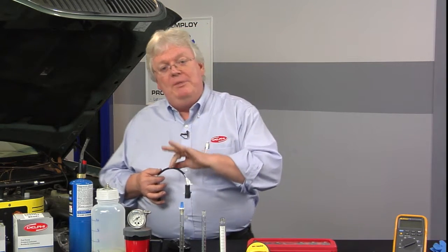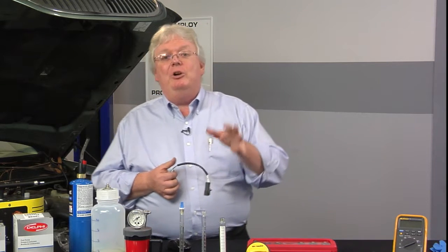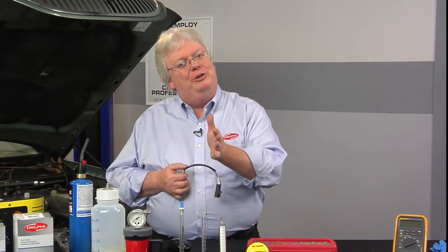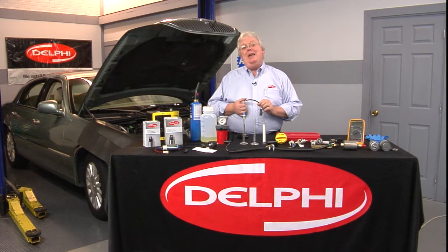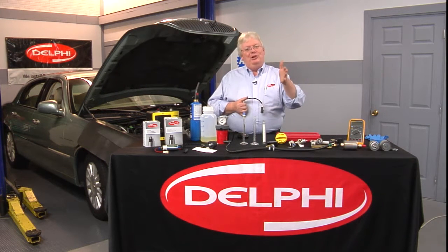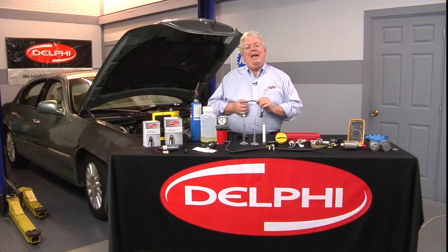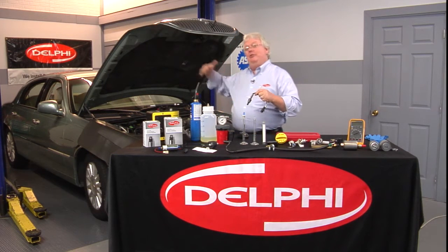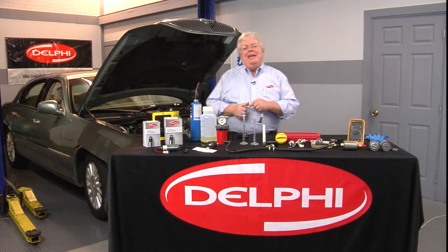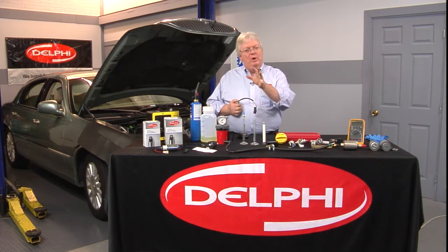So if you see a PID for total fuel trim, but you don't see one for rear fuel trim, you see short term, you see long term, and you see total fuel trim, and the total fuel trim does not add up to the short and the long added together, it's a number higher or lower. It's because the rear fuel trim, the after-the-catalytic-converter O2 sensor, is driving that total number for whatever reason.